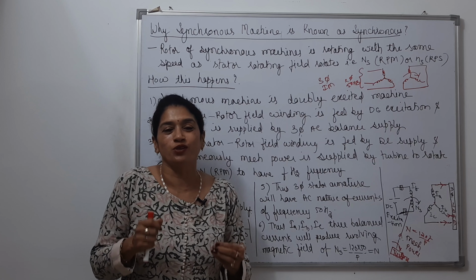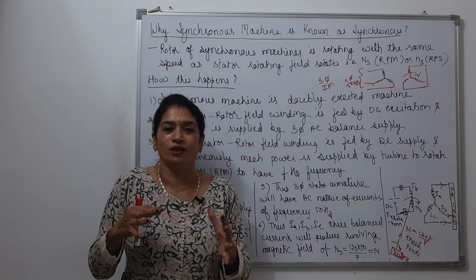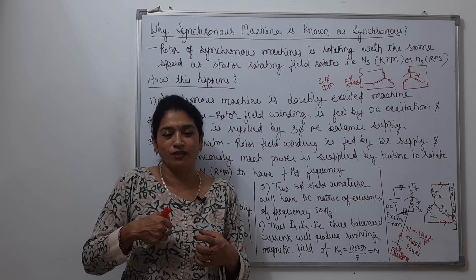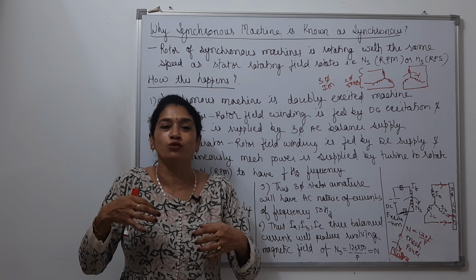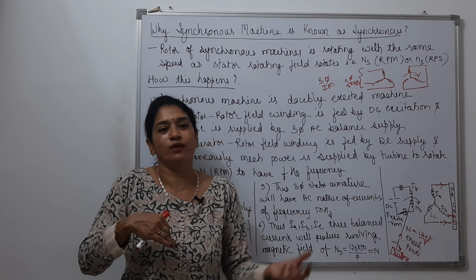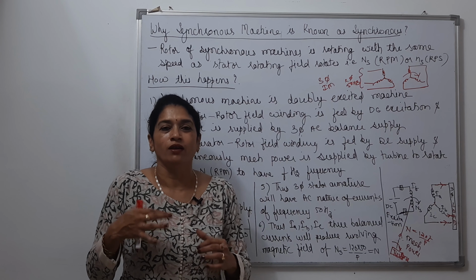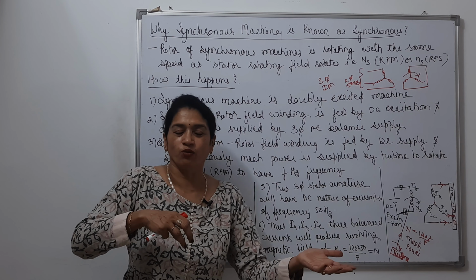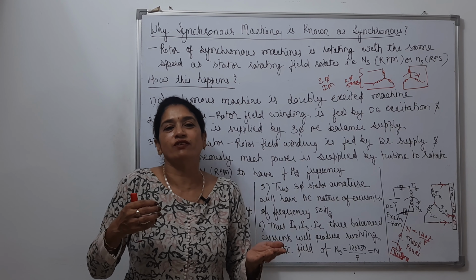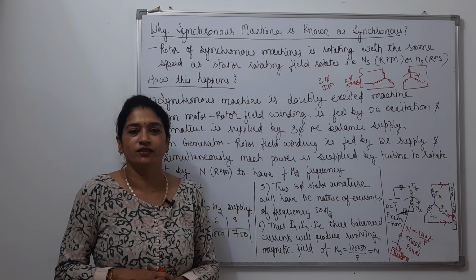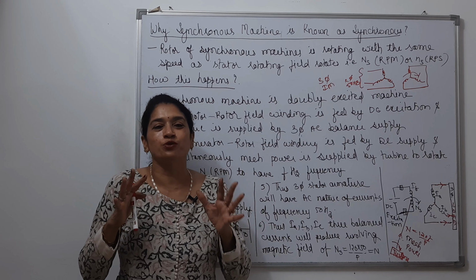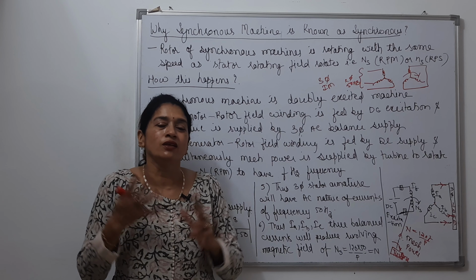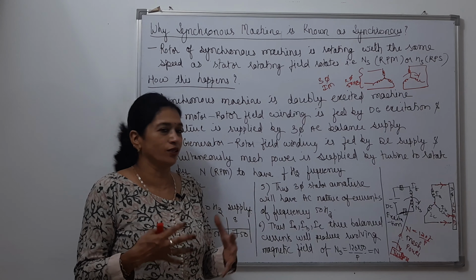And the same sort of logic I apply in a transformer: if the primary side is fed by some AC power and the secondary side is also fed by AC power, then there would be an addition of the two fluxes produced due to the primary power and the secondary power. There would be an addition of power. And if only one side has a supply and the second one is the utilizer, then the second side will develop a flux which would oppose the primary side's flux. Whatever I am telling you, please go through the playlist of dot convention in the Hindi version, so that you can understand better what I am telling you right now.